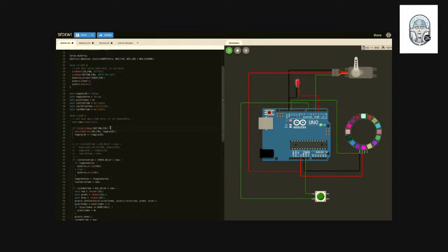Oh, it's because I changed the state each time. So, right. So as long as I hold down the button, it is working. We wanted it to toggle. And it's most likely we have to debounce it. So for a push button like that, you will get an on and off reading. So what you do is you average out the readings if you're getting it consistently off or consistently on.